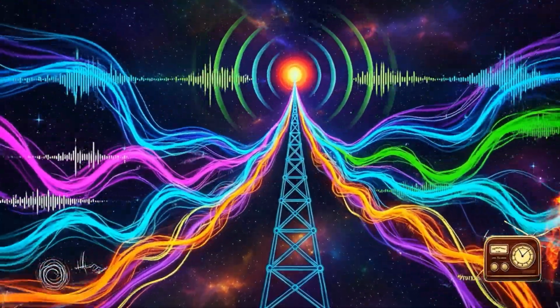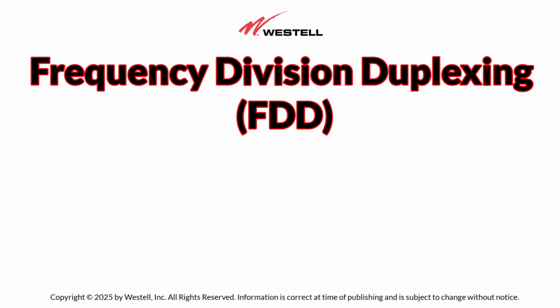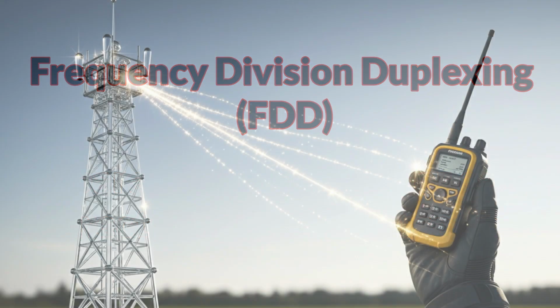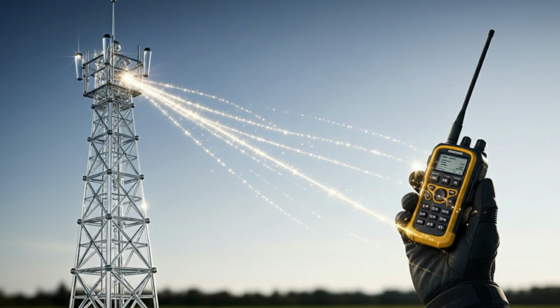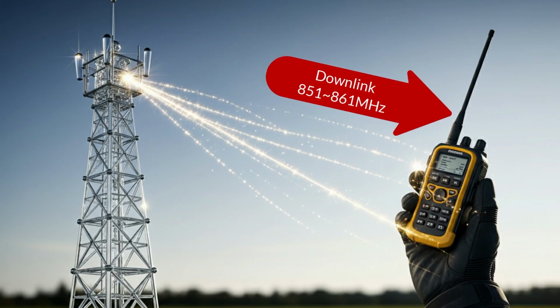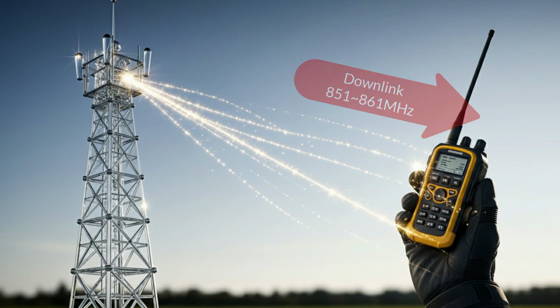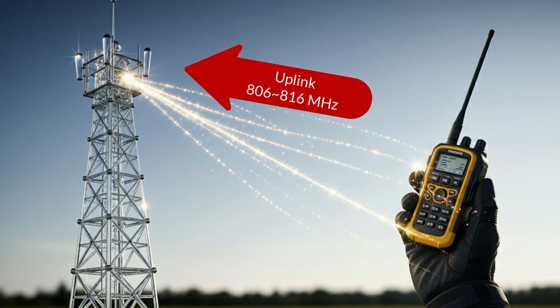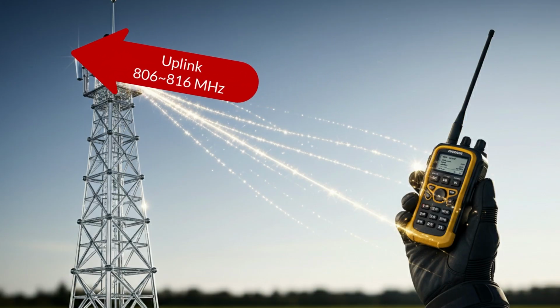One common method of radio communication is frequency division duplexing, FDD, which utilizes two separate frequency bands for each direction of communication. For example, in public safety networks, the 800 MHz band is frequently used. The tower's outgoing signals, known as downlink, typically range from 851 to 861 MHz, while signals sent from a portable device to the tower, known as uplink, usually operate within 806 to 816 MHz.